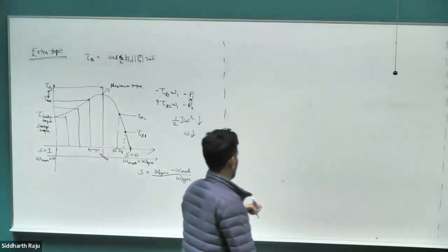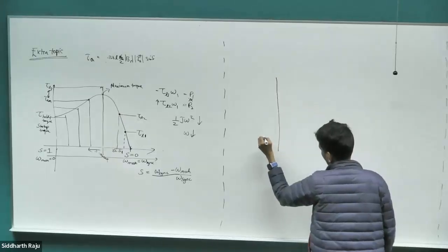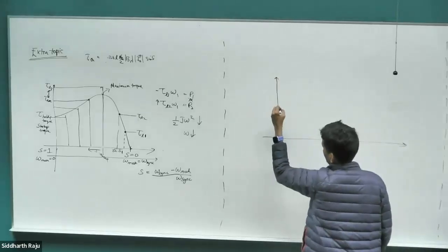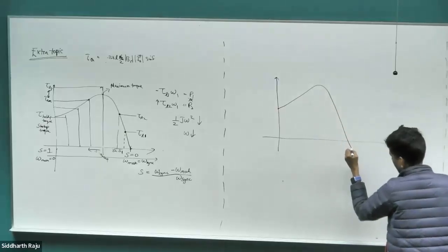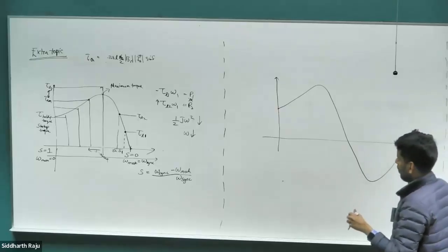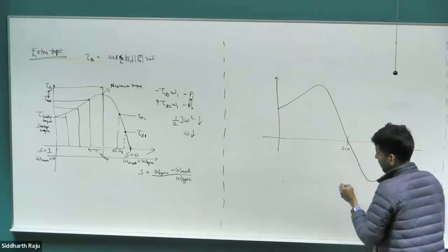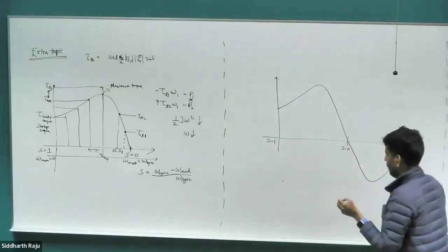What does it mean when the slip becomes negative? If you plug it into our equation, the torque-slip characteristic curve equation that we derived, the negative slip would basically recreate the same waveform all over again. So this is slip equal to 0, and this is slip equal to 1. So what does it mean to have negative slip?